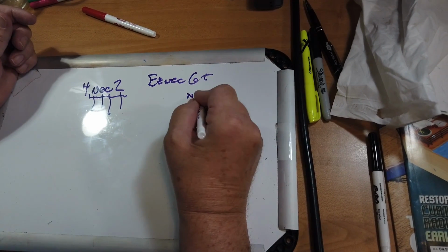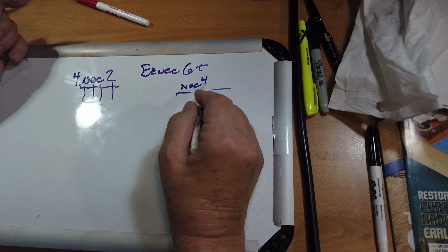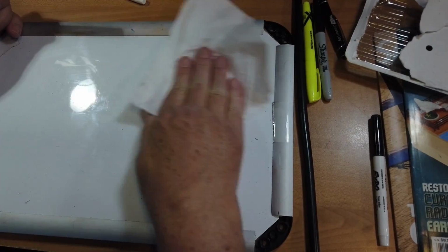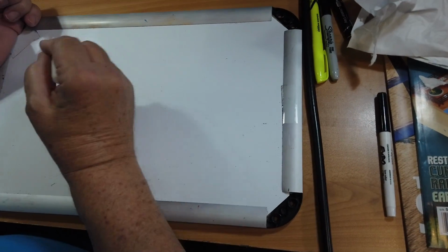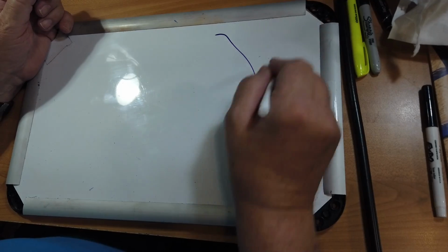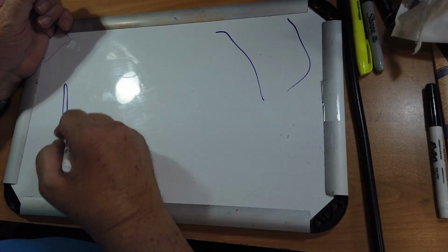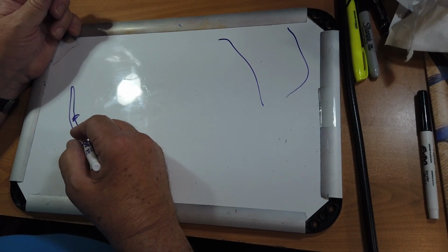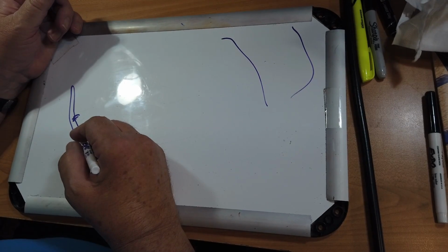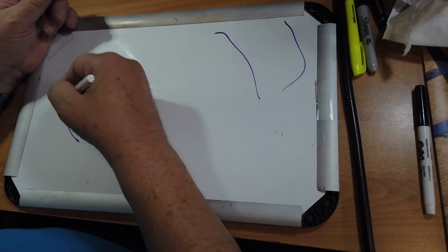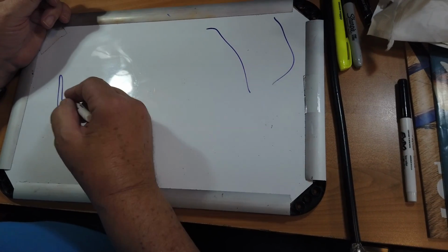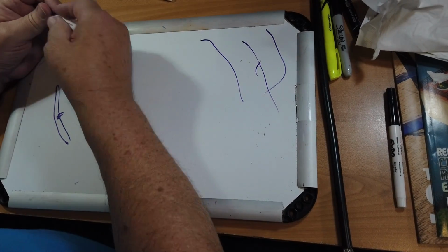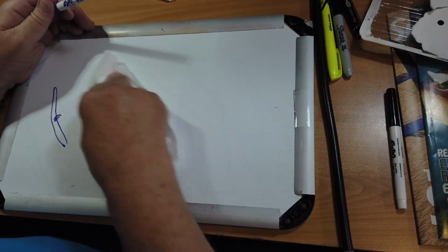Now there is an NEC4, but it's proprietary. You have to pay a license for that. NEC2 is in the public domain. So the point being that to determine what the far field of an antenna looks like, you need to model, you know, like if you've got a dipole like that, a folded dipole, you model it and you discover what the patterns are. And you get 2 patterns that you can look at.